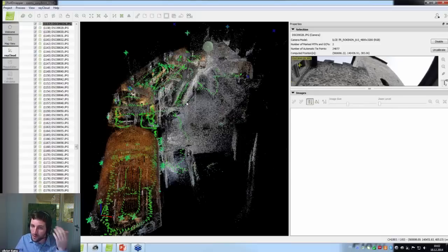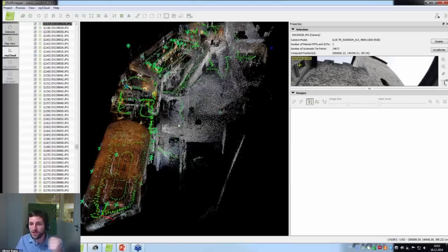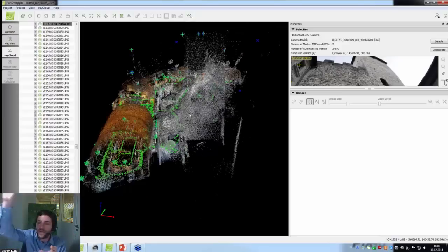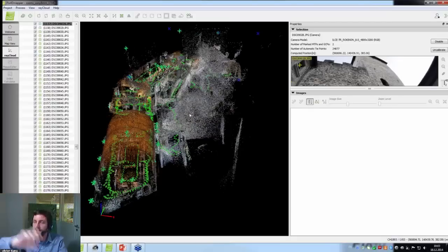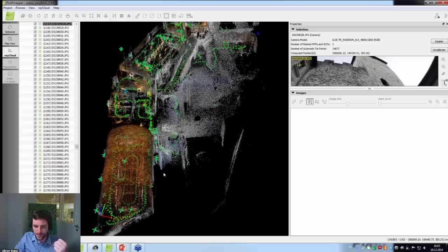And then if you need more accuracy on the ceiling part, then there's no other choice than going closer to the ceiling. And this either using a drone, a UAV, or by taking a ladder and finding a more manual way to get the camera closer, or taking a stick and getting the camera closer to the ceiling of the object. But the fisheye is really what makes it possible to take the images in a very, very nice and easy way without having to think too much about how the images are taken.